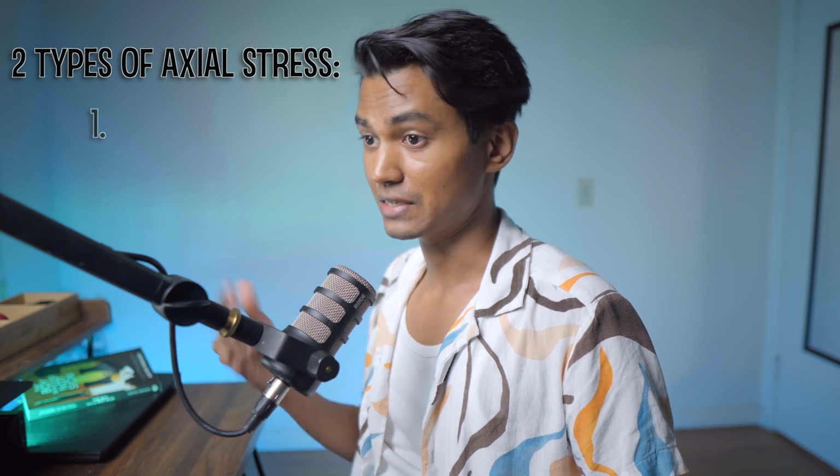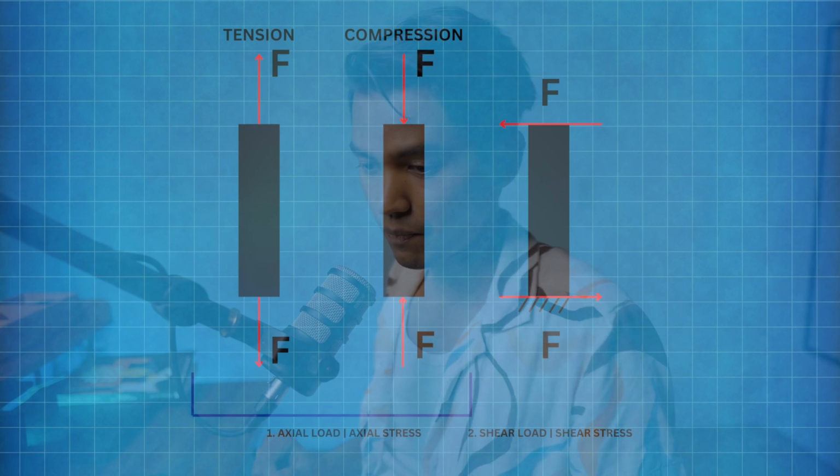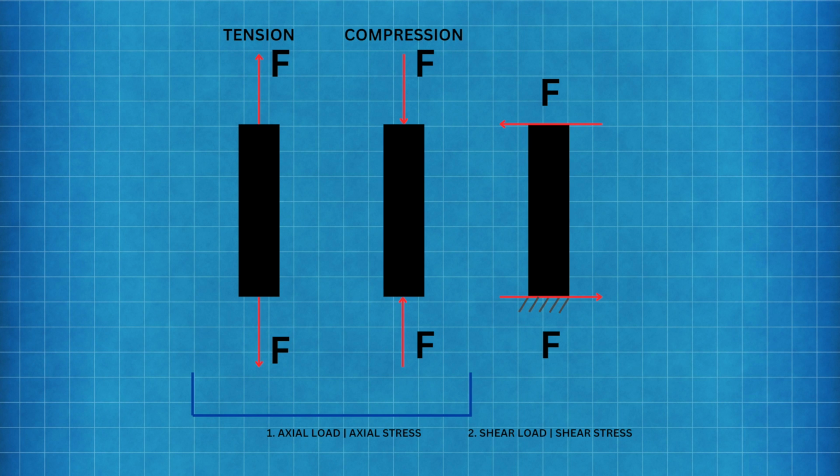Shear stress is different because the force is parallel to the surface. So let us say this is my surface, force is parallel to the surface, that's shear stress. Force is perpendicular to the surface, that's my tensile stress. Area is also a vector, force is also a vector. The relation of these two vectors' directions matters.